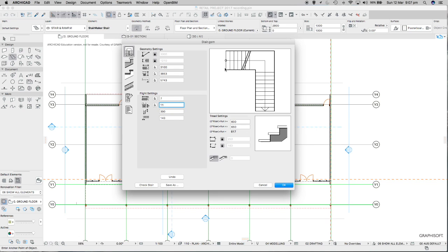If you had the handrail going on the inside here, you'd want to start getting close to evening up so that by the time the handrail left this rise, it was a standard riser dimension by the time it got all the way around the corner to the next rise. That would assist in setting out a continuous handrail. It just makes it easier for the fabricator to do a continuous handrail, which is a requirement for these stairs.